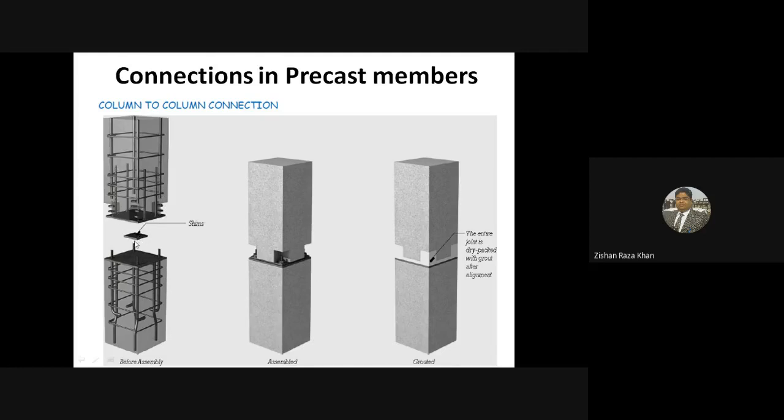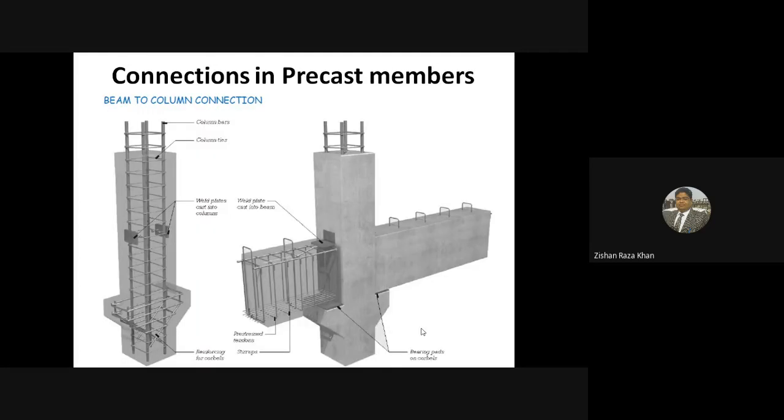And this is the central connecting piece. Put it together just like a key so that it will hold its location, and the concrete pillar is attached like this. Okay, so at these corners you just install a bolt in it and tighten it. And after connecting, you just fill it with grout. So after painting, it will look like a continuous column. This is how a precast connection is made in concrete. And similarly, the connection between column and beam can be made like this.